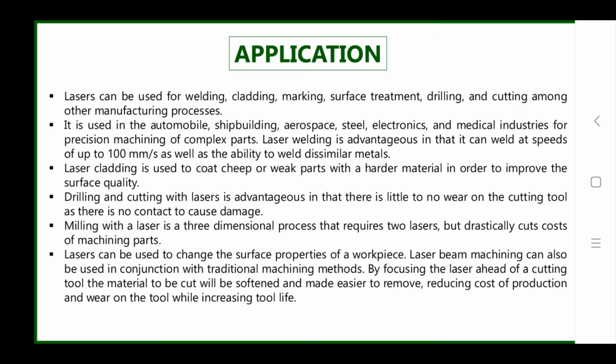A laser can be used to change the surface properties of the workpiece. Laser beam machining can also be used in conjunction with traditional machining methods. By focusing the laser ahead of the cutting tool, the material to be cut will be softened and made easier to remove, reducing the cost of production. So this is about laser beam machining.